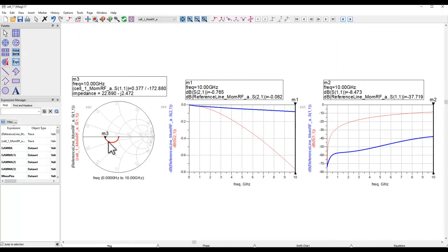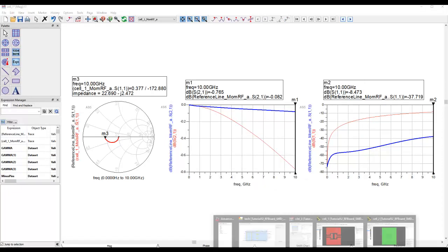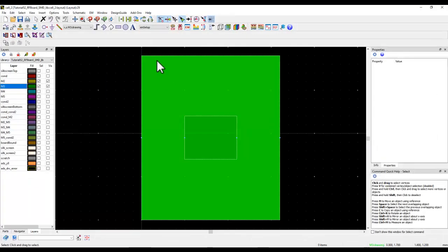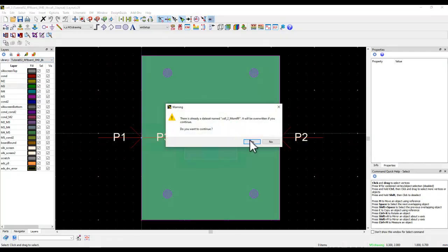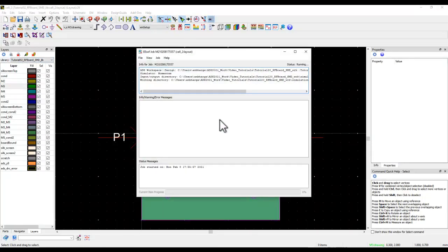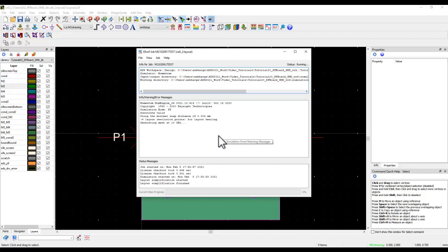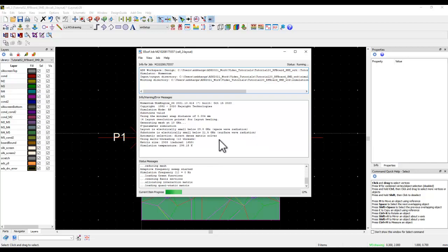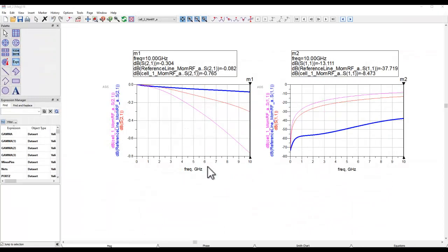That means if I create the slot and perform the simulation again, which I'm going to do now, in cell 2, if we go ahead and run an EM simulation, I would expect a better return loss compared to what I achieved earlier when I was using M2 as my return path. So let's give it a few seconds and the simulation will finish, to verify our calculation, or how things work in RF microwave or high-speed digital design.